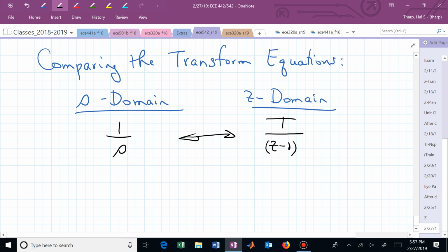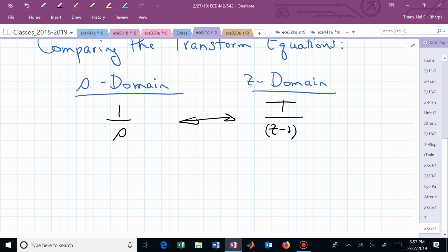There's the connection. Or maybe it's not as straightforward to always be talking about reciprocals of s. We can now invert both sides, and we can say the relationship between the s domain and the z domain using the forward rule of numerical integration allows us to say wherever we see an s, we can replace it with this factor z minus 1 divided by T, and we can now generate an H of z from an H of s.